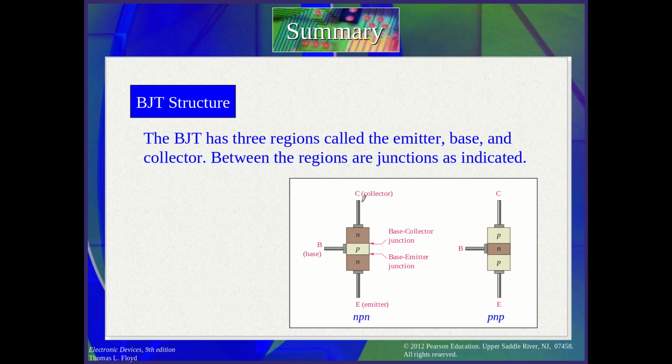So when there is no incident light here, then this is off, and the normal Q2 is working because it is in forward bias. There is current in the base, and there is a current on the relay.